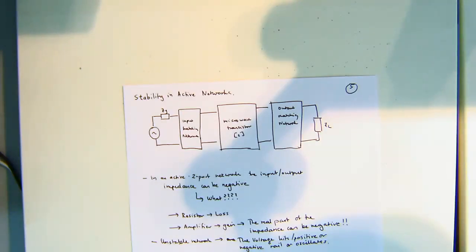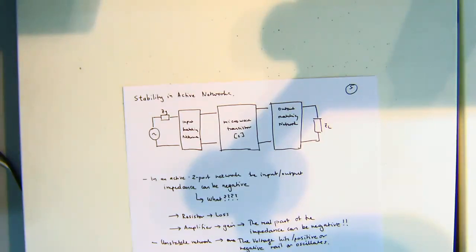The truth of the matter is, as we discussed yesterday, it's never going to go, in the long term, above or below the positive and negative supply rail. So you should always think of it as usually bound between the positive and negative supply rail. Sometimes you might have a little bit of inductance and go a little bit above the supply rail, but let's forget about that.